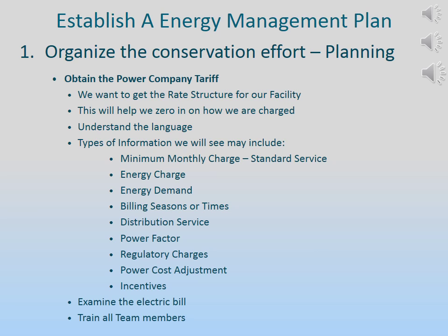With most utilities, their basic charge is going to be the higher charge. Then, when they go above a certain amount, it becomes less expensive. When we go to save, we are then saving at the cheaper rate in a tiered structure. So that is why it is important to look at our structure, because if we are going to calculate what we are saving and a payback period, we need to know at what kilowatt hours we are saving. Are we saving at a cheaper rate or do we have a flat rate?